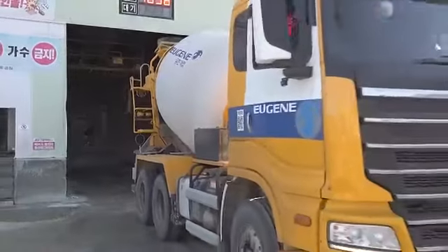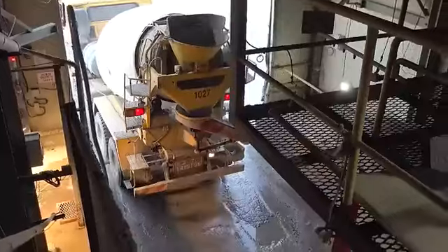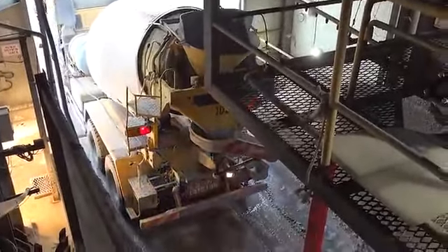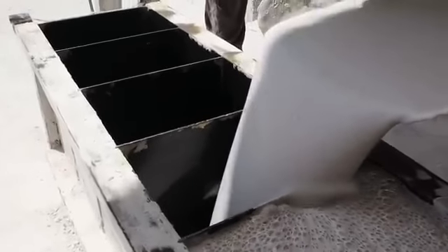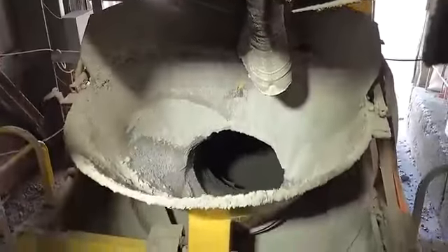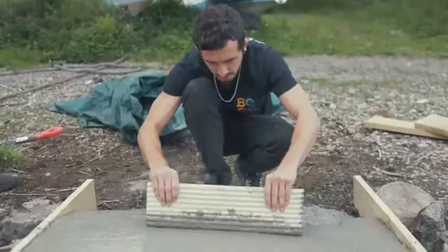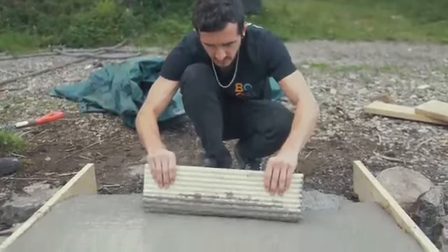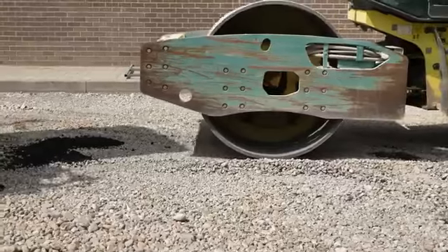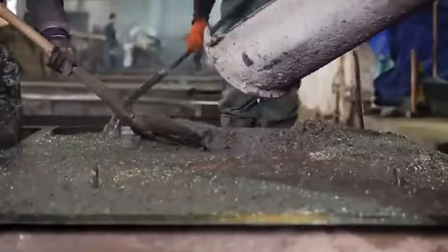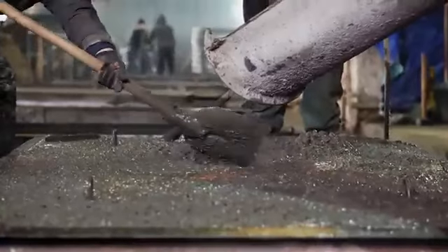Once the concrete is mixed and has the desired consistency, it is transported and placed in its final location. This can be done by pouring it directly into formwork, molds, or by using specialized equipment such as pumps or conveyors. During the placing process, it's important to avoid segregation, which is the segregation of coarse aggregates from the rest of the mixture. After the concrete is placed, it needs to be properly compacted to eliminate any voids or air pockets. This is typically achieved using vibrators or by mechanical means such as tamping or rolling. Compaction ensures that the concrete is dense and has good strength and durability.